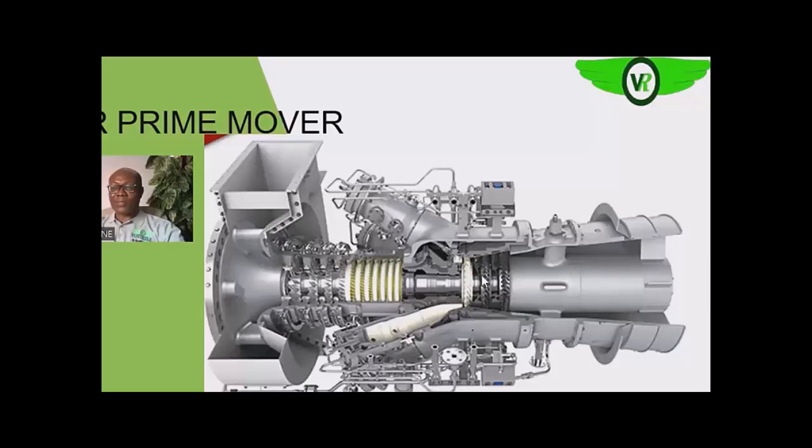These are the turbine blades. As the fast moving combustion product impinges on the turbine blades, the kinetic energy contained in it is extracted by the blades and forces the rotor to turn, the way your fan normally turns when it is hit by fast moving air. That is what happens around the turbine blades here.